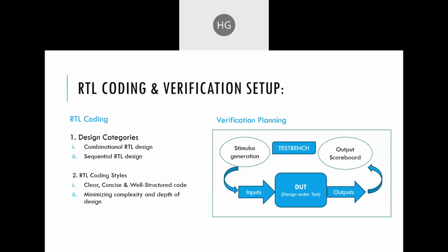In the verification, we have one reference model, or you can say there is one specification, with which I want to check. So there are two values: the actual value, which you get as the output after running the simulation, and a reference value. You compare the reference value with the actual value. If it is wrong, then the scoreboard will show, hey, you're testing this scenario, and the output you are getting is wrong. Then you again need to do something here.